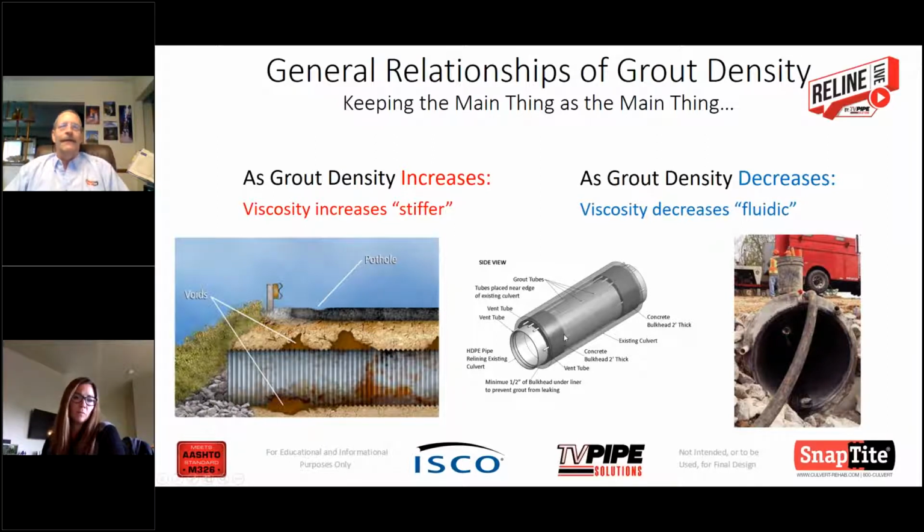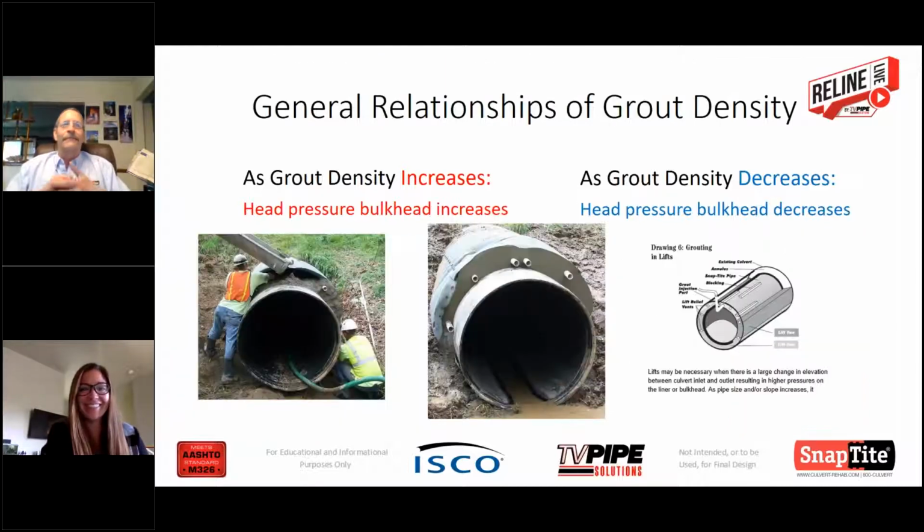And if there's anybody that thinks that a stiff grout product is better to use in this installation, let's talk after class, because I think you must understand something that I'm just not getting here. The next one we wanted to talk about is the head pressure that occurs on the bulkhead during the grout placement. And in this RPS system, your bulkhead becomes a structural member during the installation process.